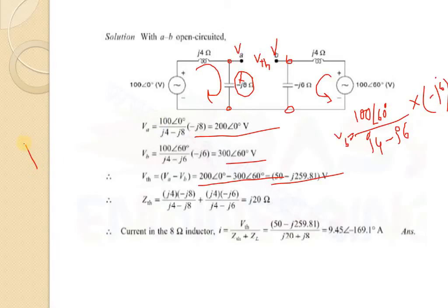This is short, this one is j4, this will be an inductor, then this is minus j8, then here it is RTh, again here another XC with value minus j6, then another inductor, and again this voltage source is removed and the path will be replaced by its internal resistance, that is 0. So it is again shorted.